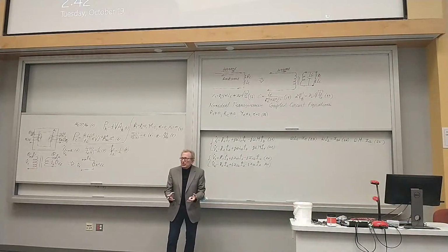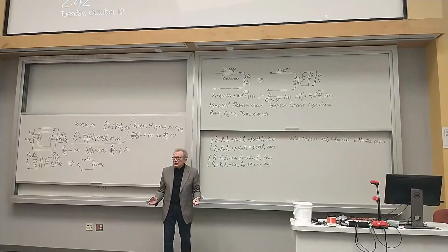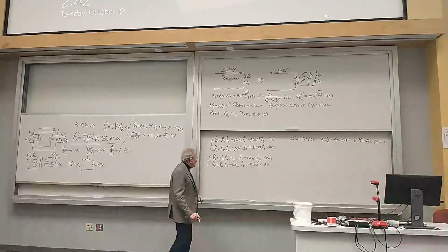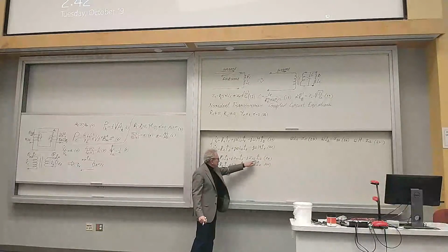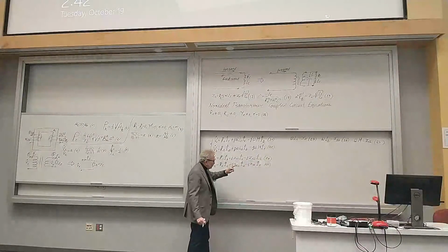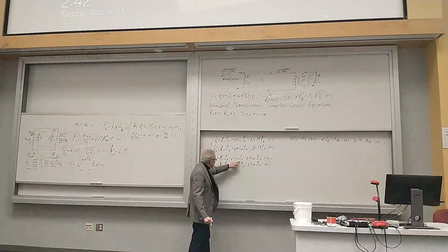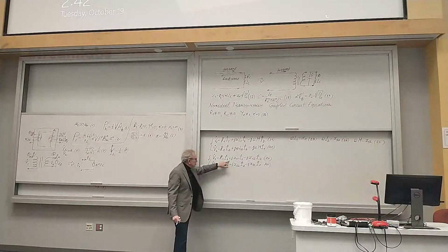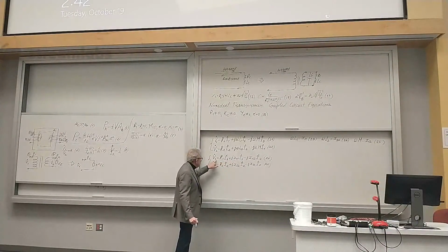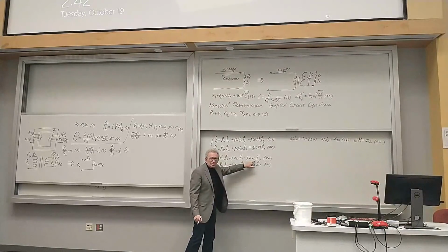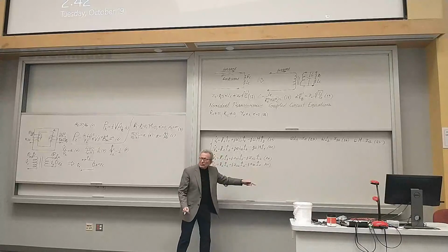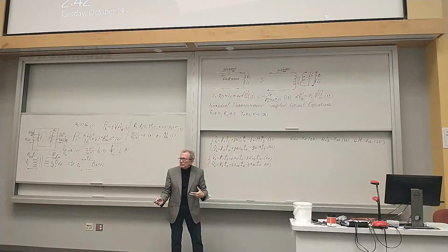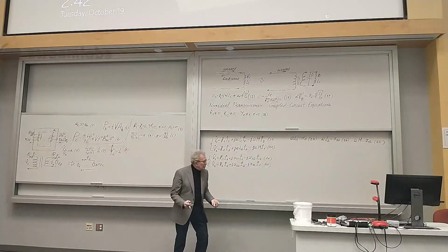Without the primary voltage, there is no excitation of the transformer. So in order to find this, I will find the expression for the primary current in equation 26 in terms of the primary voltage and secondary current. And then I will substitute it here instead of I sub 1, and I will get this relationship between the secondary voltage and the secondary current, and a known primary voltage.